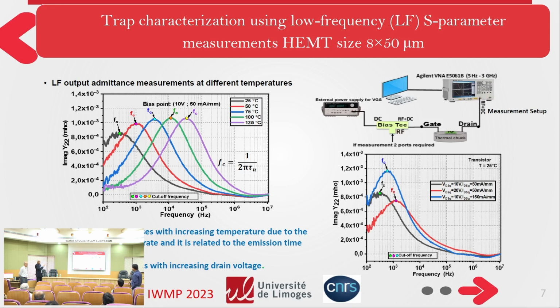The bias is always limited. But we compared the admittance measurement with the S-parameter measurement and obtained almost the same thing with Y22. That's why I say with Y21 it will be difficult: we have to do the calibration seriously and properly, make a lot of measurements, and be sure of that.